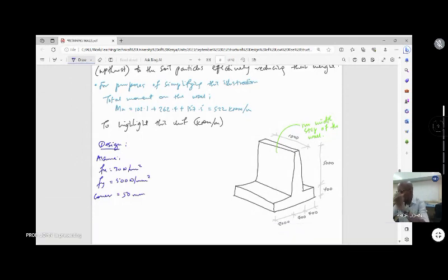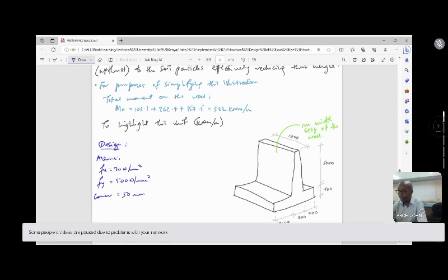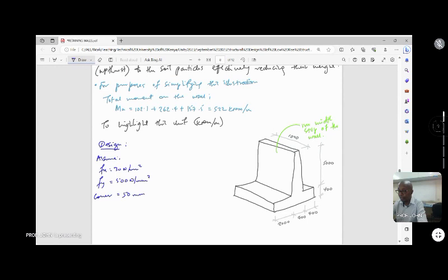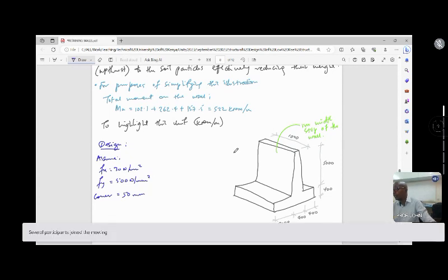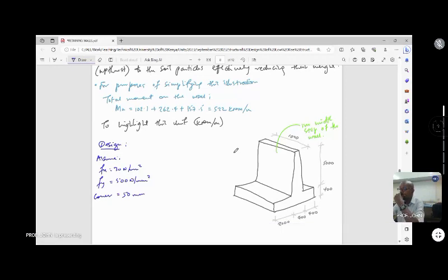Foundation elements, because of the ground conditions, are considered to be more aggressive than conditions above ground. Then the minimum, I think, from the BS is about 50 millimeters that you can provide for cover.